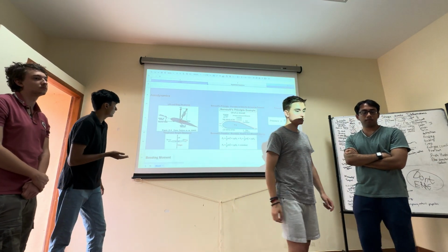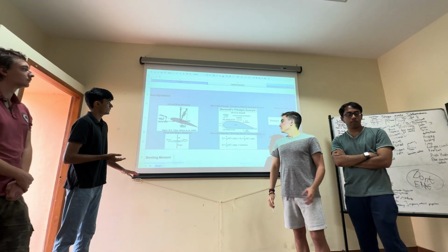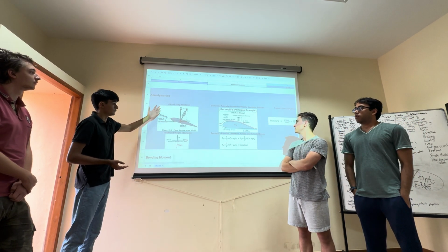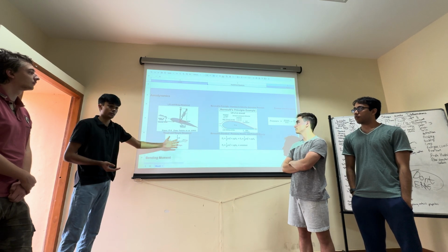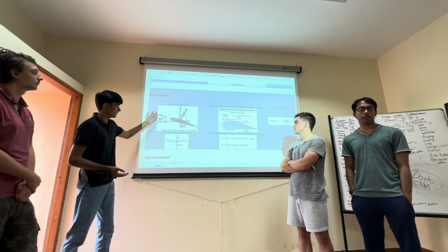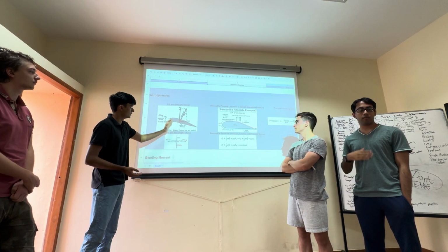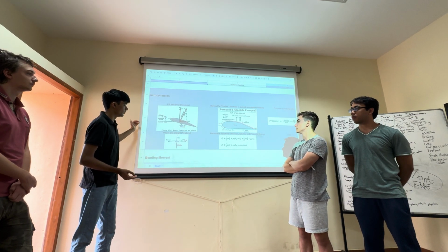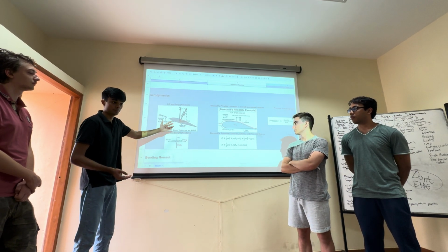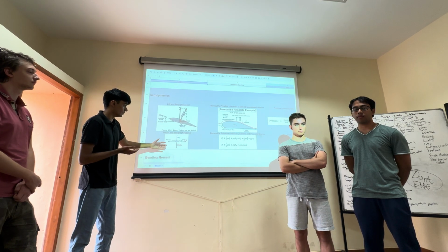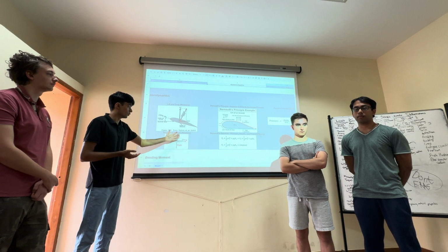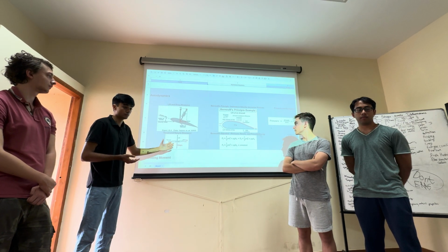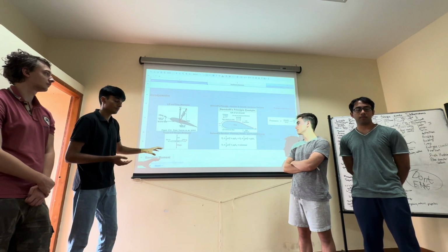Okay. So let's talk about aerodynamics. Very simply with loads, we can talk about lift and drag, thrust and weight, all in newtons, right? So we see that applied on an airfoil here with lift and drag directions based on the direction of the velocity of the fluid. And then here we have a basic diagram of a plane with the four major forces that are applied, if we were to zoom out, right?